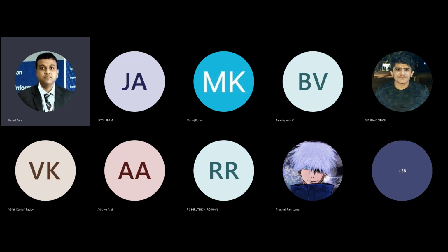Here the partial operator will be there, because the displacement function, let's say u or v, for the beam is the transverse displacement, that is the bending deformation. V is a function of space as well as time t. So the governing equation of motion involves a partial differential equation, and the analytical or closed form solution only exists for a very simple, uniform system without much complication.